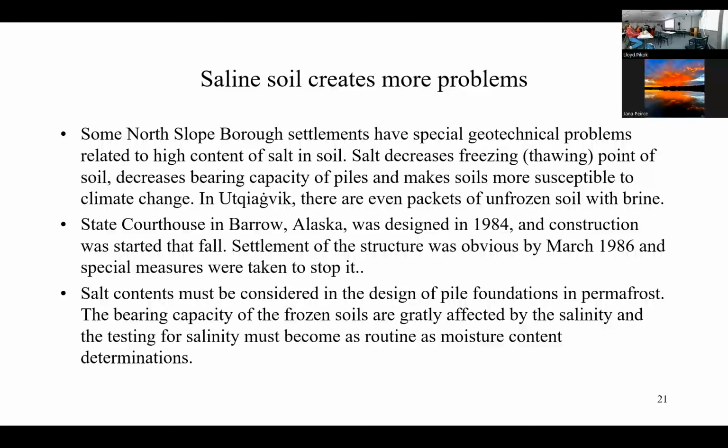Again, it was described in the literature that when they built the state courthouse in 1984, settlement occurred practically very soon after construction. Under one part of the building, the geotechnical investigation found a package of brine, very saline soil.